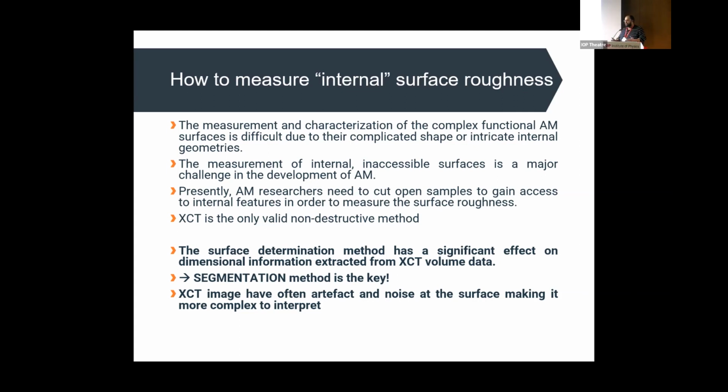Obviously, you don't want to destroy your part each time before testing it, because then you don't have any parts left. So this is why X-ray CT is the technique. It's the only valid non-destructive method. But when it comes to X-ray CT, you have other questions to answer, mainly about the surface determination method. We know that it will have a significant effect on the dimensional information that you will be extracting. So basically, everything is about segmentation here.